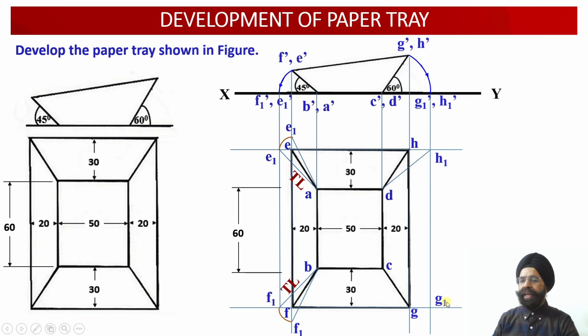So now we can see how we have obtained this point H1. From point H1 dash, we have drawn a perpendicular projector into the plan projection view, and wherever this vertical projector from H1 dash, it is going to intersect with horizontal projector drawn through the point H. So this intersection point has provided us with the location of the point H1. And once we join DH1 over here, so this is the true length of the edge DH obtained into the vertical orientation.